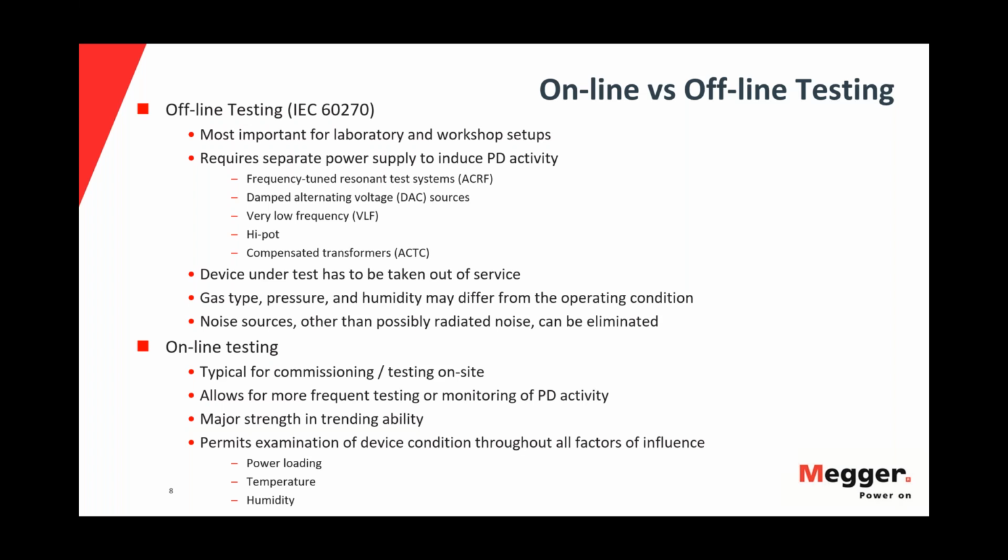But if it is above U naught, that means the PD won't happen initially but may be ignited. Depending on the level of voltage, we can find out if that can ignite it during the start of the transformer, inrush current. With the extinction voltage also, we can find out if that can be eliminated quickly or will sustain. So all of these factors are benefits of offline testing.